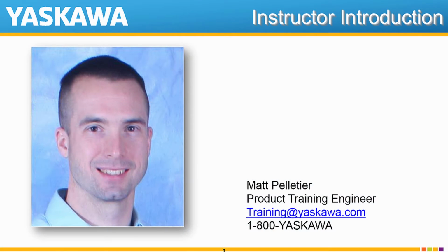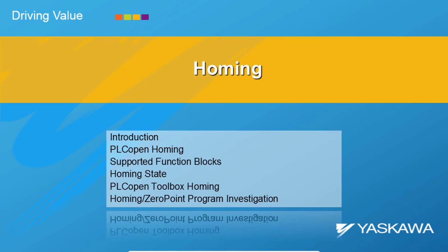Hi, I'm Matt Pelletier. Let's proceed in the class project to build an automatic homing routine for each axis. We'll use home pulse for one axis. That's a block from the PLCopen toolbox. And on the other axis, we'll do a simple 0-point set.